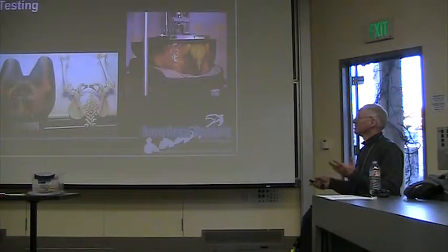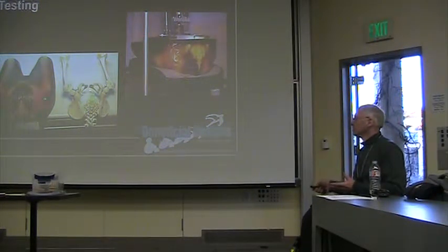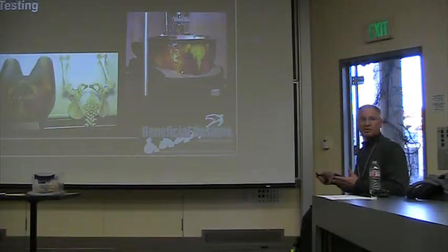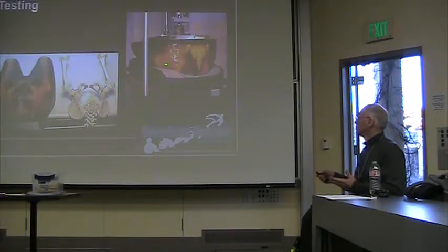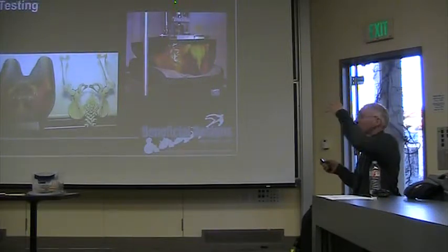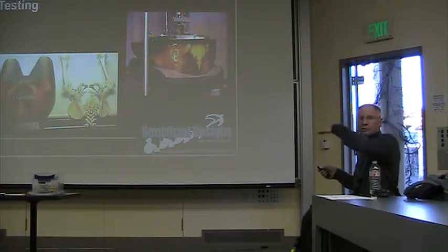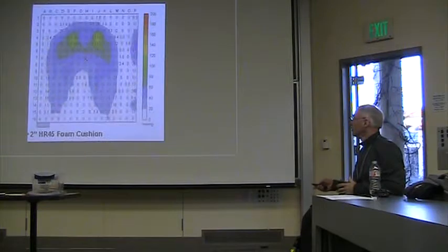And so we designed what we call the Skelly. It's a skeleton embedded in gel to be able to test the seat cushions. So we would put the gel and load it in with a crank it down and measure the force we're pushing it in with. And then we would measure the pressures.